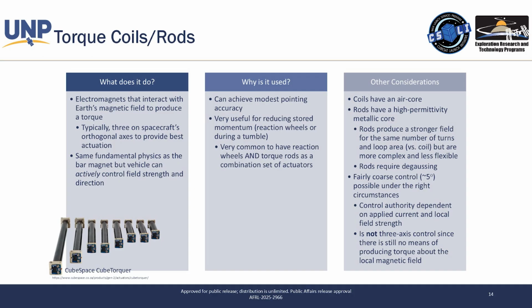That third direction, we can't ever really do anything there. That's what makes it under-actuated. You only have 2-dimensional control, not 3D, so you're not a true 3-axis stabilized system. You can't really control the spinning about the Earth's magnetic field line, and that depends as you go throughout orbit. As that changes, you can still sort of control the spacecraft, but it's still not fully 3-axis controlled.